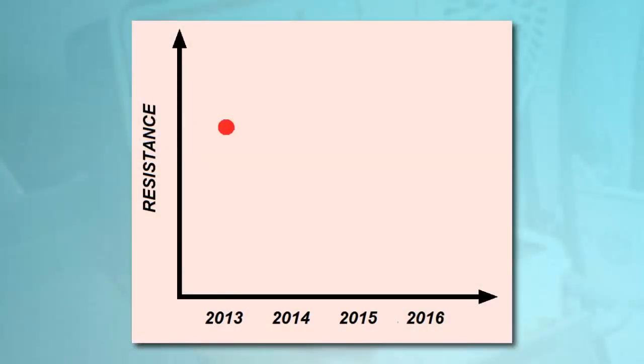For example, suppose you perform a spot test every 6 months. Plotting the results on a graph, you observe a slow and gradual downward trend, as would be expected by the normal aging of insulation. However, your latest measurement reveals a sudden drop in resistance. This is likely an indication that the insulation has begun to deteriorate at an accelerated rate. To address this, you can schedule downtime for the system and take appropriate measures such as cleaning, upgrading, or replacing